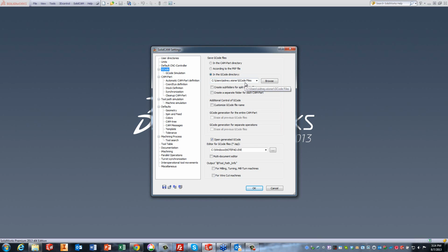If somebody has a part in a different location under the same name, a copy of it, makes a change to it, and then you replace that part with this part, you will not keep any of your SolidCAM data in there, because it's a completely different part. It's within the part itself, and you're just changing the part. However, working in assembly mode remedies that situation, and we'll talk about that in a few moments.